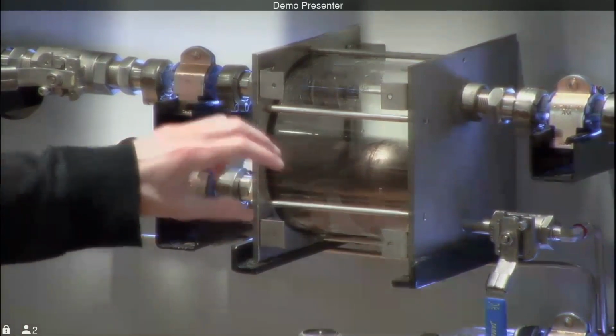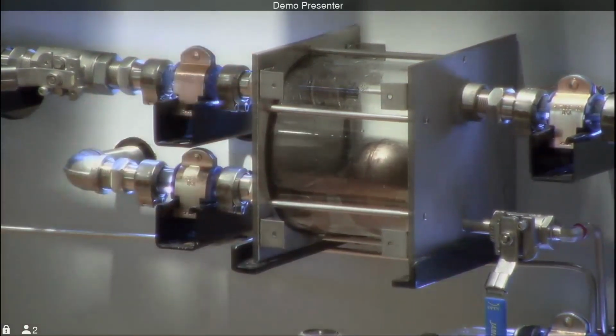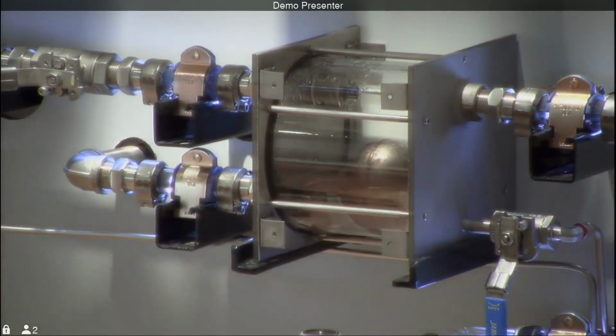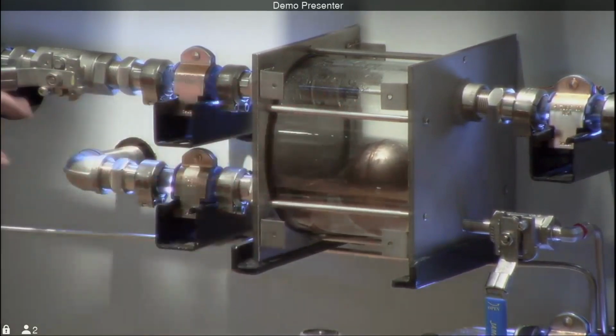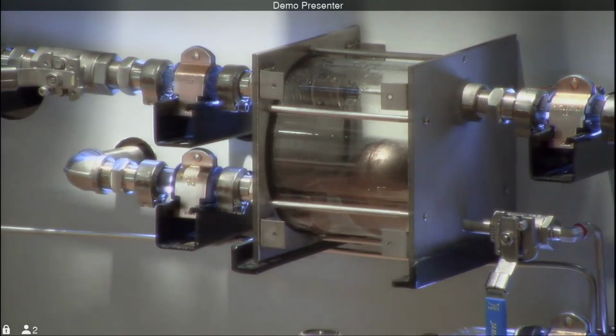Also, the float and the bellows are weak points in this trap, so either of them could be collapsed or ruptured from water hammer or freezing. If the float collapses, it's not going to be buoyant anymore, so the trap's going to fail to close because we're not able to discharge anything out of the orifice. If the bellows is ruptured, and that's typically what will fail first, then usually it fails open, so in that case, steam would be blowing through into our condensate return line.